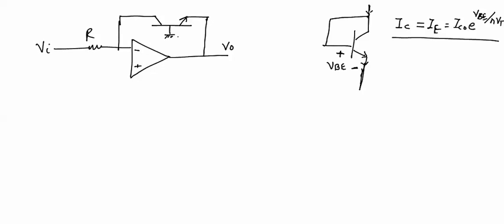Now we have this transistor here, base is grounded, and as this non-inverting terminal VP is grounded, then by the virtual ground process Vn will also be at zero potential. So here base and collector are at the same potential, so this transistor can be used as a diode. Here we will have two currents, this current IC and this current I. Again we will apply KCL at this point, so IC plus I will be equal to 0,